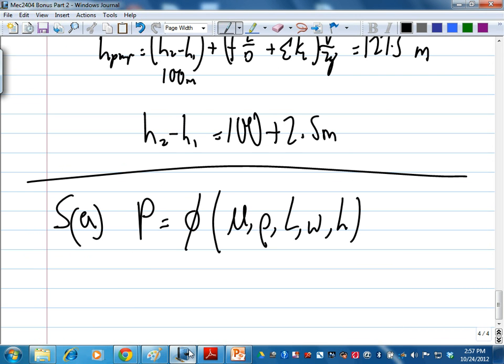Alright. So you need to choose. I will tend to choose rho, L, and omega. Right? Because I told you choose rho, the length, and the velocity. In this case, there's no velocity, but there's an angular velocity. That's also dependent. Alright? You choose rho, L, and omega. You could choose the diameter, right? That's the diameter, is it? Okay, no problem.